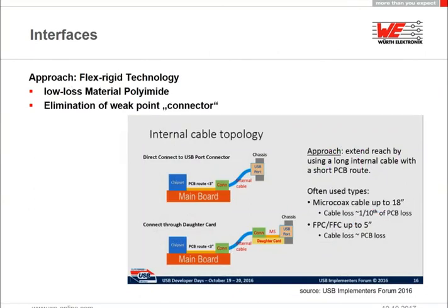Using Flexrigid technology at the same time means usage of low-loss material, which is called polyimide. So this thin foil, flexible material, shows pretty good performance regarding high frequency. So we will see some figures afterwards. And again, the point of using Flexrigid technology is that we can avoid the weak points, the connectors.